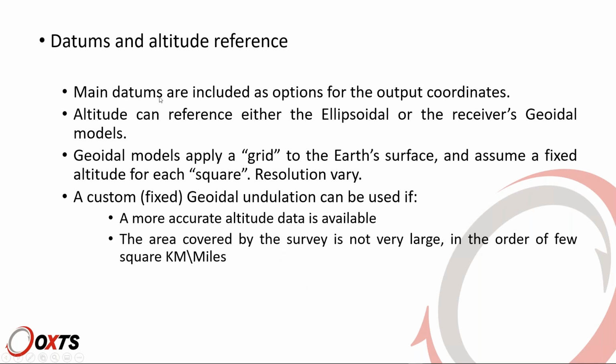You can have different datums: NAD 83, that's suitable for North America, ETRS 89 for Europe, WGS 84, that's global. Depending on what exactly datum you want to refer to, you have a number of options with our systems, which can be useful at times so you don't have to convert that later.